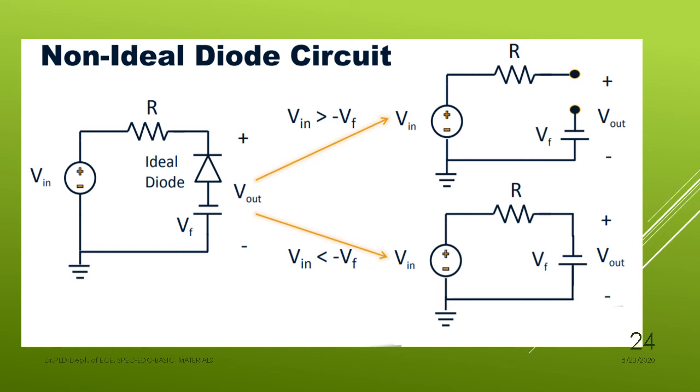If the diode becomes forward biased, it acts as a closed switch. Because of this, it is closing. If it is closed, the output voltage is the same as the forward voltage source voltage only. That is, the output voltage equals Vf.